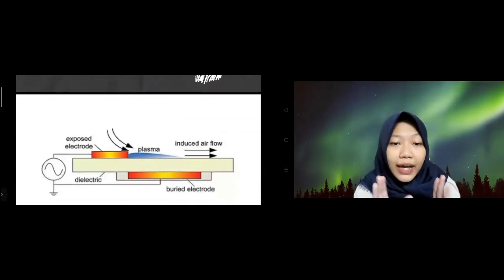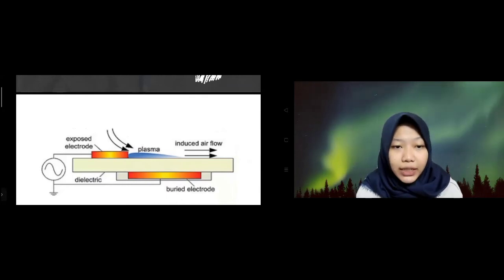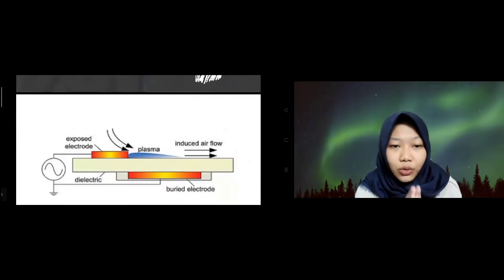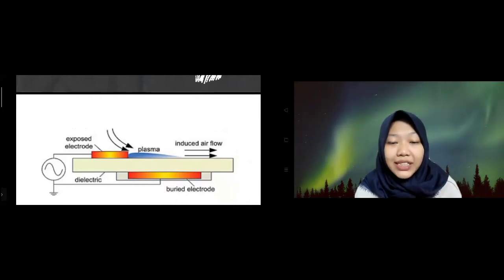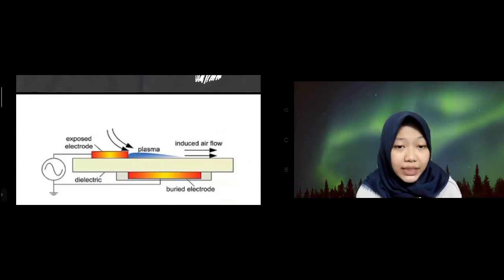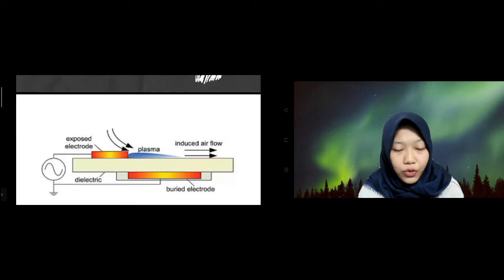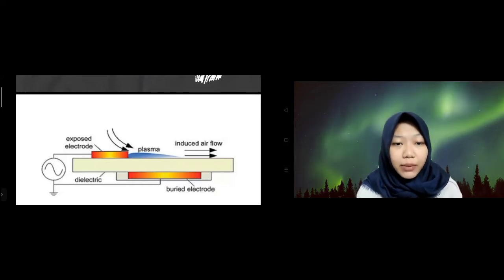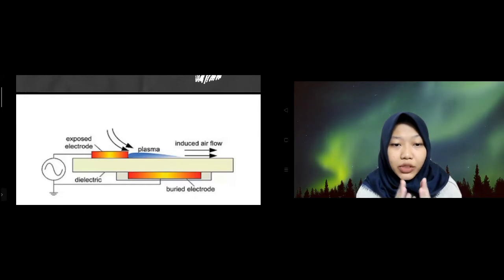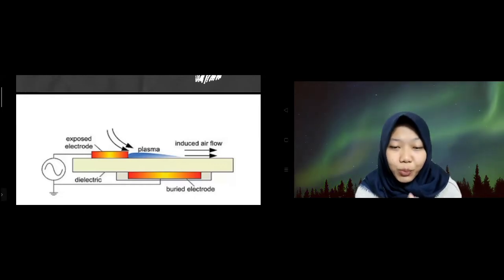Plasma flow control has drawn considerable attention and been used in boundary layer acceleration, airfoil and turbine blade separation control, axial compressor stability extension, heat transfer, and high-speed jet control. The recent invention of glow discharge plasma actuators by Gross in 2003 can produce sufficient quantities of glow discharge plasma in atmospheric pressure air, which helps to yield an increase in flow control performance.